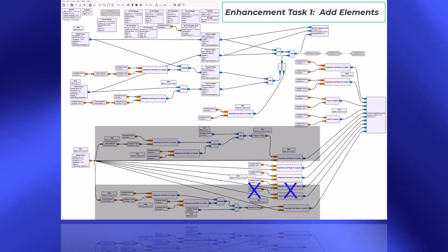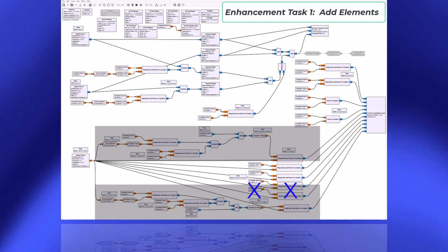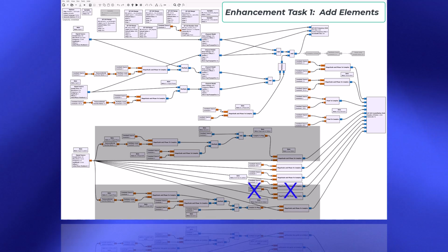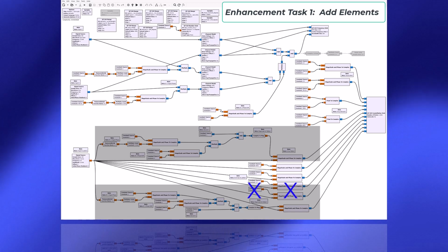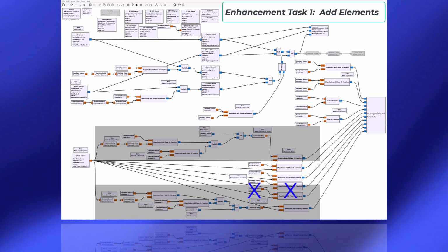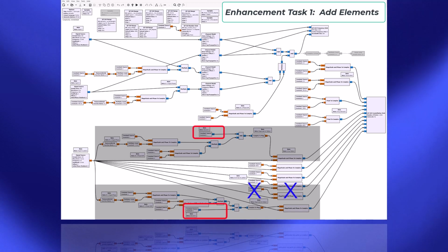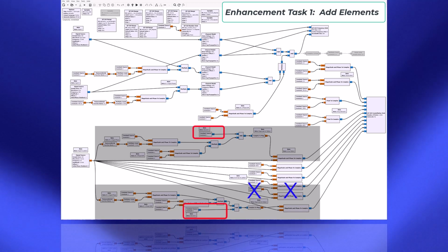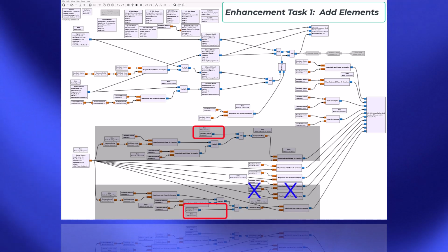Each of those is used to generate an array pattern that includes the combined effect of the element positions and the inter-element phase shift, but not the effect of the geometry of the transmitter's angle of arrival of the signal. Therefore, each of these collections of blocks that's used to generate an array pattern includes a signal that represents the reference element, and another one that represents the second element with the inter-element phase shift applied.